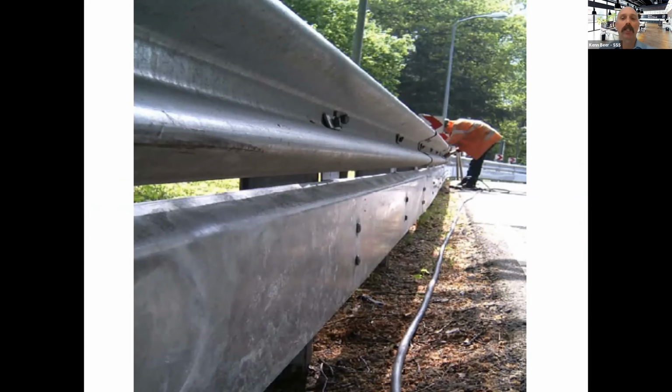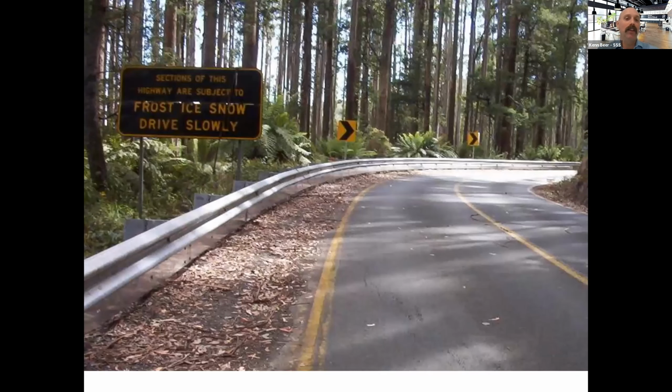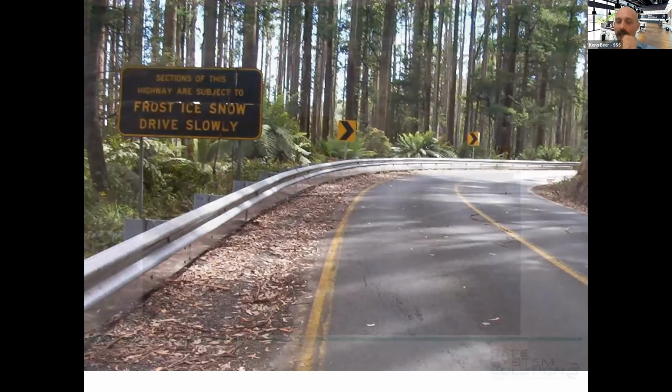But each flexible W-beam product has their own proprietary motorcycle underrun protection device, and the suppliers will gleefully tell you all about them if you ask. If you're sliding along as a motorcyclist at 80 or 70 kilometers an hour, you would not want to be hitting one of those posts. If it was retrofitted, it would be better to hit that and slide along it and dissipate your energy. And these have been tested and shown to be fairly effective. I'll show you shortly what the tests are.